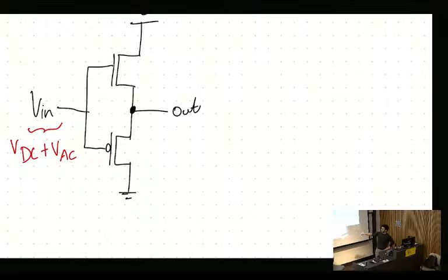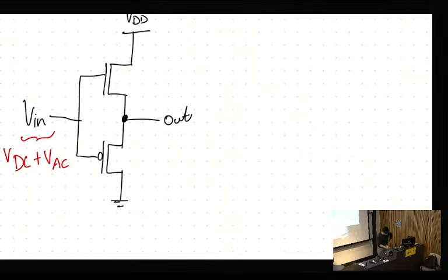The amount you're allowed to fluctuate this AC signal depends on the transistors and when they turn off and on. So transistors have strict conditions for which they stay on. The first being that the gate-source voltage must be greater than the threshold voltage. But then there's the other condition about the drain-source voltage being greater than the gate-source voltage minus the threshold, the effective voltage. So you'll see that in a past paper. I don't want to go into too much detail here, but effectively, you can't just swing this infinitely. At one point, you swing it too high, and the transistors go out of their correct range, which for a MOSFET is saturation.